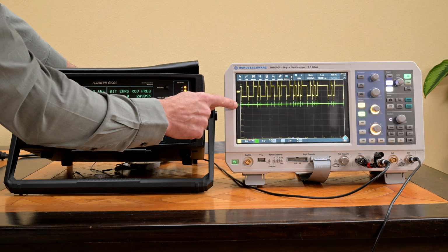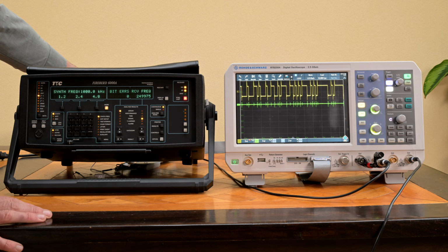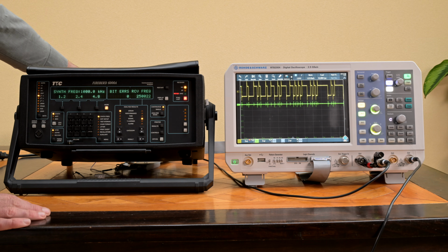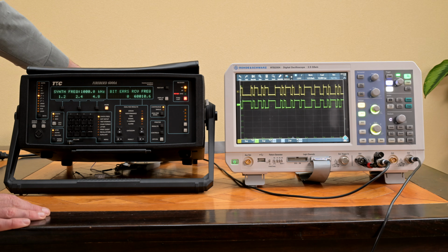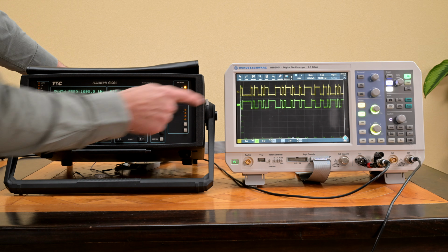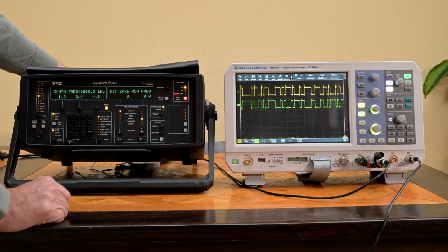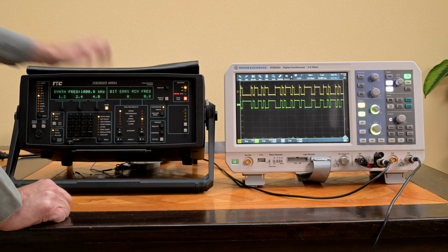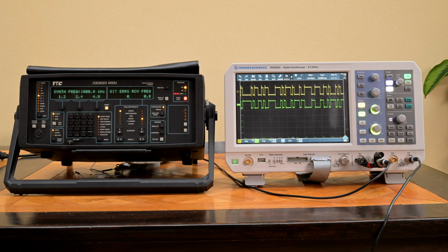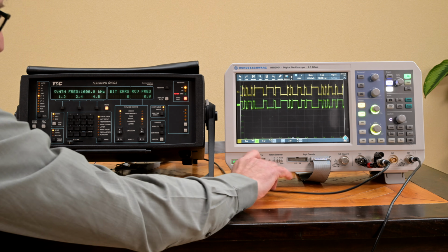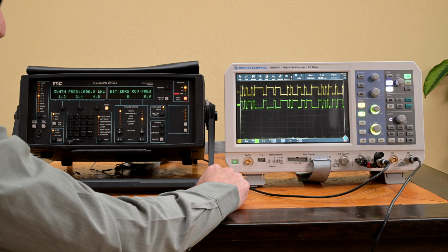And mind you, we're still getting to see the type of ringing here, even on the connector that is not used. And in the fourth position, we get a combination of both, and both signals are basically bipolar type of signals, and they are opposite. And this opposite allows us to make a balanced type of signal. And this balanced type of signal is great basically to remove any noise that it picked up on the road.